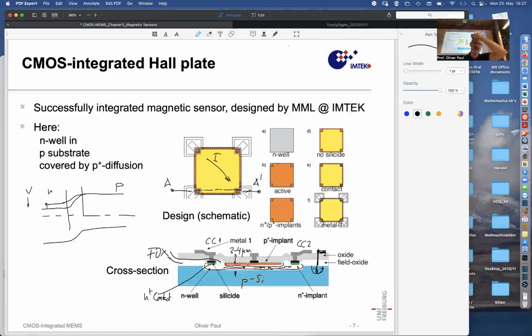Then we need some regions that need to be silicided. So for instance, these contacts need to receive silicides, or need to be silicided where the future vias will be. But then also we would like to contact this P plus region, this reddish region, not in the center, but along the rim, like indicated here by these little dots that indicate the via contacts, the P plus contacts.